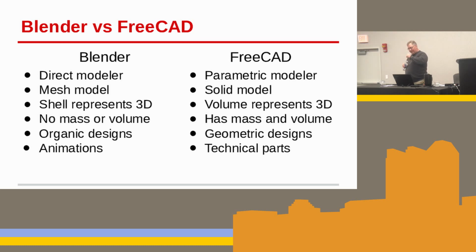Blender and FreeCAD are fundamentally different in that Blender is a direct modeler. In Blender, when you build models, you're working directly with a mesh. You can think of a mesh as a shell that you're constructing to represent your 3D object, and that shell won't have mass or volume simulated as part of its mathematical model. It's very good for organic designs.